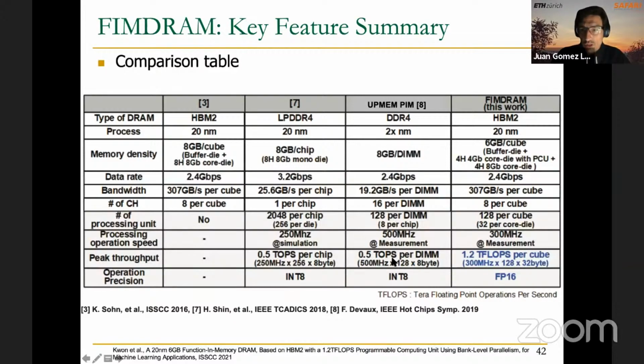And then peak throughput is also quite different. So I don't think that this is something that is really representative. It's good to have it as a theoretical maximum value to consider and aim for for sure, but it's always necessary to move data, even if it's from the bank to the register file, or in the PIM architecture, from the MRAM bank to the WRAM.